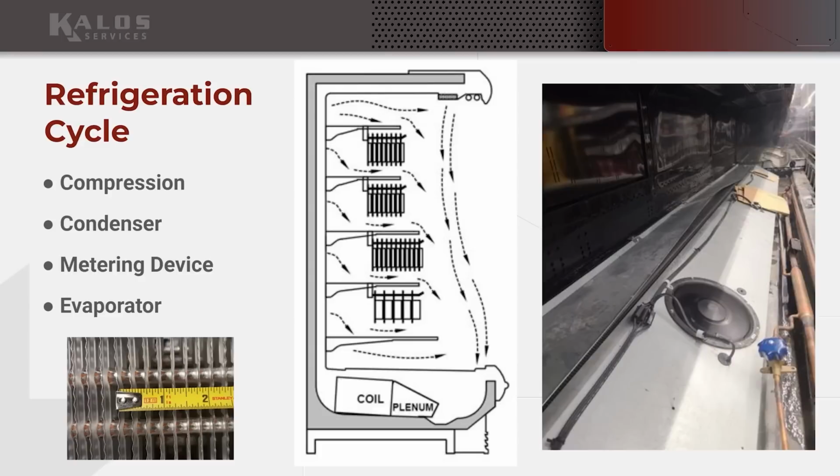I'm going to take about half of that airflow, and I'm going to pressurize the back wall of this case with that air, and about half of it is going to come out of these little holes that you see all along the back. Okay, that's going to leave about 50%. That's going to go over the top, and it's going to come down.